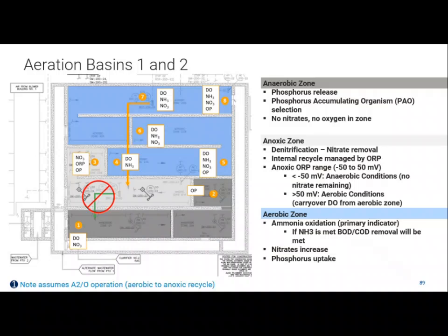Maybe it's listed in here even. No, it's not listed. But it's like a big ceiling fan or a box fan in your window on a pipe, because you're not pumping against a lot of head. That's the thing. When you're pushing from here to here, it's not like you're lifting the water up a lot, right? Think of a pump station, like your RAS pumps, where you're lifting that water out of a well back to the head of the aeration basin. You're lifting it up feet. Here, it's like an inch. So you're really just pumping against the head loss in the pipe. So it's not a huge horsepower, right?